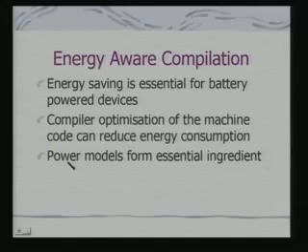So energy aware compilation is an important feature for embedded appliances, and in fact this interest and concern has grown of late in recent years because of the availability of a number of battery powered devices. Now for such compilation, the power models form an essential ingredient. What is a power model? A power model represents a model which encodes the energy consumption pattern of instructions of a processor.